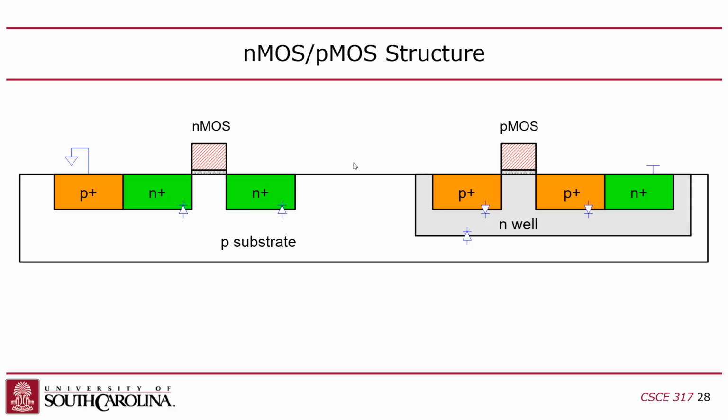And then, of course, the input to the logic gate is the gate, right? That's the gate. That's this thing up here. Okay? So I already told you that the gate is a capacitor because it's supposed to be a capacitor. That's how MOSFETs work. They're fundamentally based on the field effect, the electric field that's formed by charging the capacitor that's formed between the gate and the channel, right? Okay, so it's great that they have a capacitor on the gate because otherwise they wouldn't work, but it's bad because capacitors are slow to charge and discharge. And this kind of works against us.